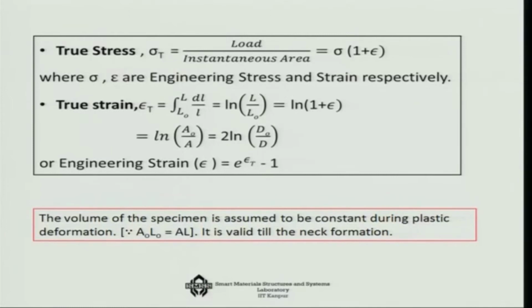So, the true stress strain curve, actually true stress is denoted by this relationship, which is sigma t as sigma times 1 plus epsilon, and the true strain epsilon t is log of 1 plus epsilon. Okay. And the relationship between engineering strain and true strain is governed by this relationship. So, this is what you can very simply obtain mathematically.